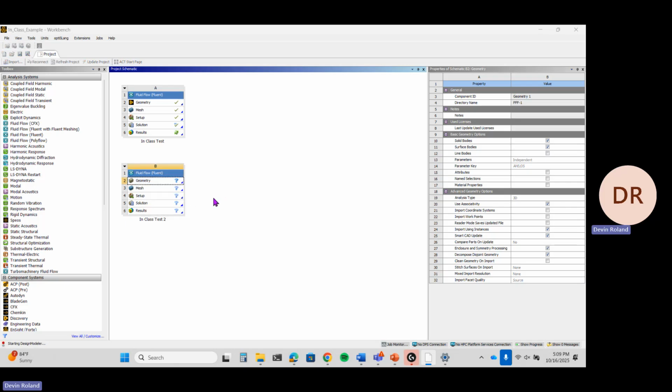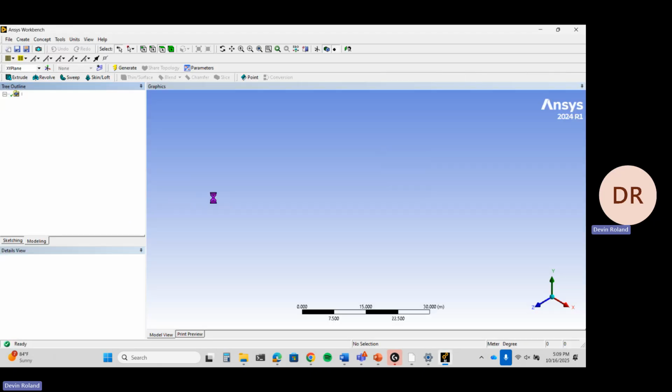So what we're going to do is similar to last time, just in 3 dimensions. We're going to make a huge block of air, like a fish tank full of water. And then we're going to create a second block inside. Then we're just going to cut the second block away from the inside of the first block to make a void. And that void will act like a solid almost. And the fluid will flow around the void.